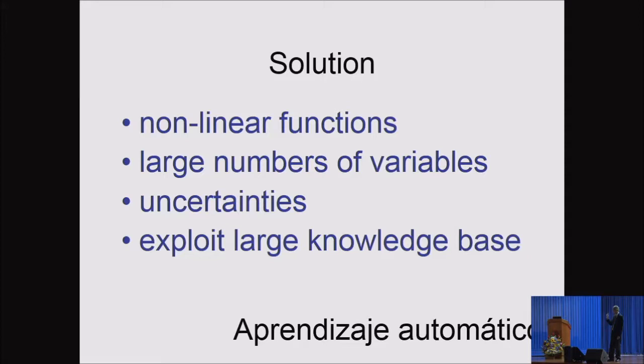And a serious treatment of uncertainties, and we exploit all the data that exists in the literature. By doing that, we can make predictions. So going back to the story of canceling residual stress, the idea is to use transformation strains to compensate for thermal contraction. And we need to generate those transformation strains at a low temperature. And that means that we should use martensite.